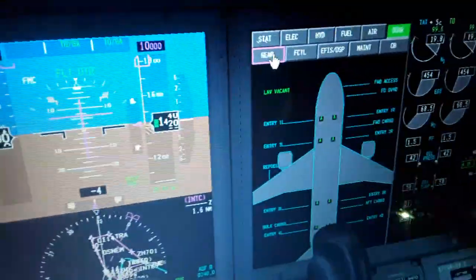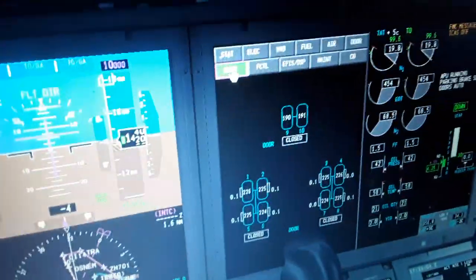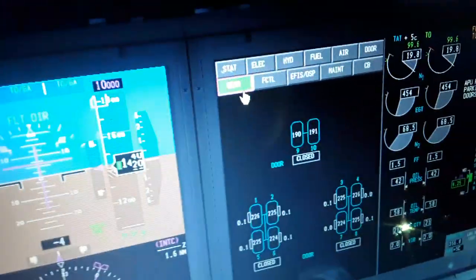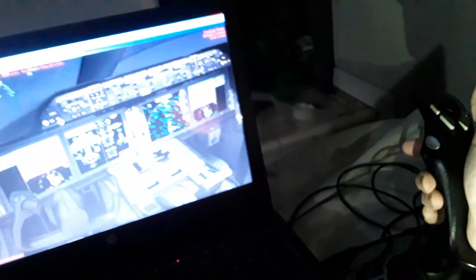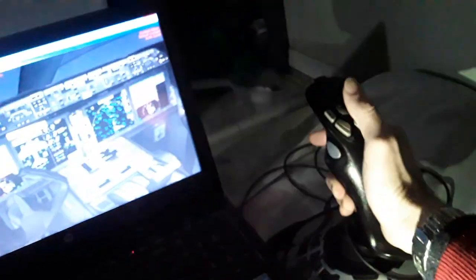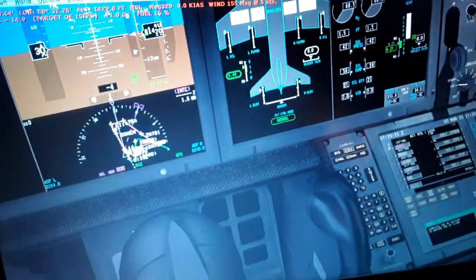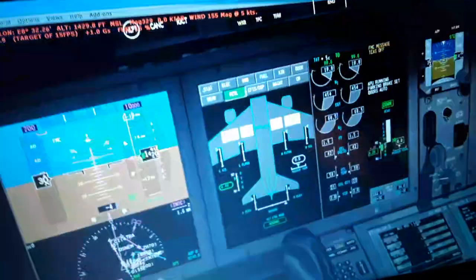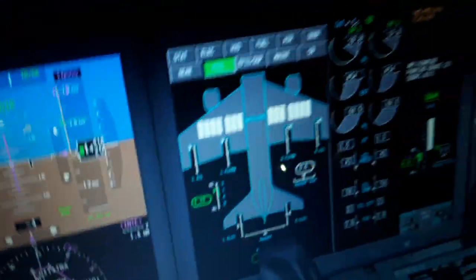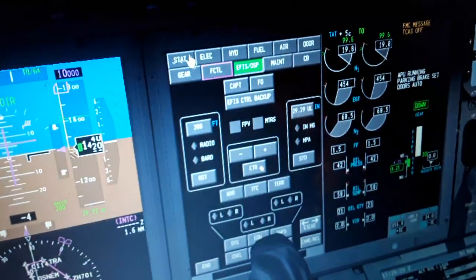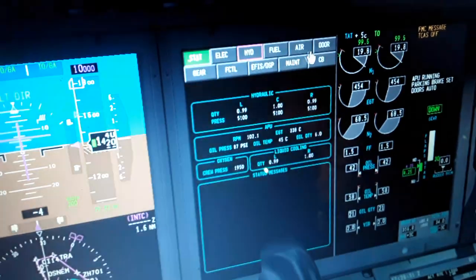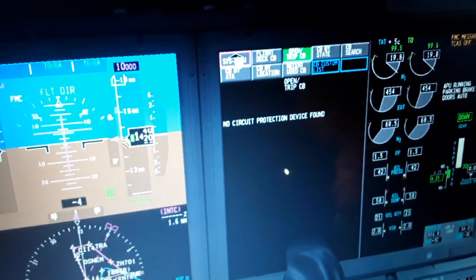The doors are closed, the cabin can be pressurized. The gear, you can see the pressure of the tires and the temperature of the brakes. Flight controls, here again, one more time, so you see all flight controls are moving accordingly. There is no malfunction. So you see also the tail here, the vertical and the horizontal tail, the rudder pedals, the horizontal trim stabilizer. F is display maintenance. Over here, digital and circuit breakers also.